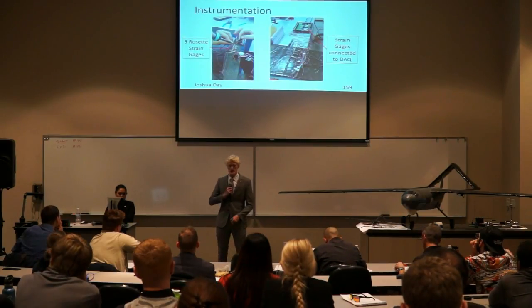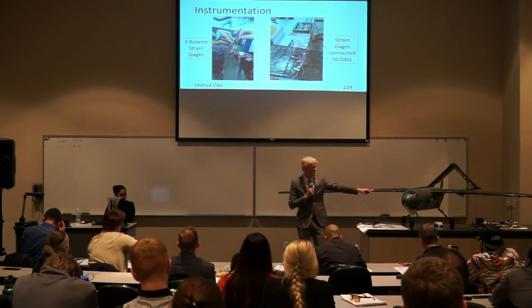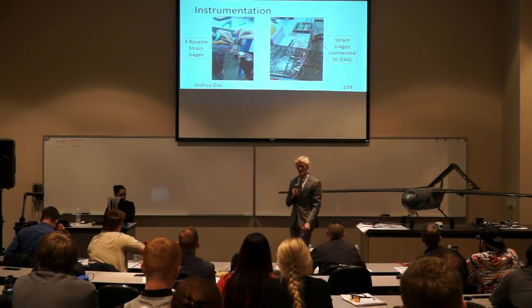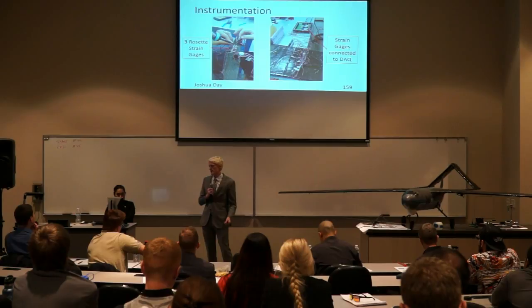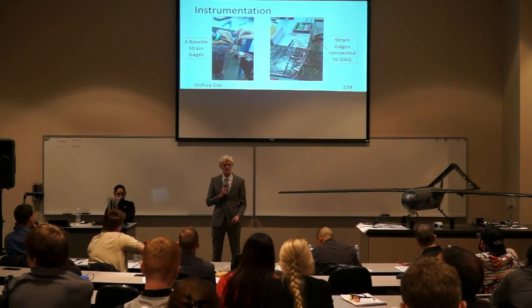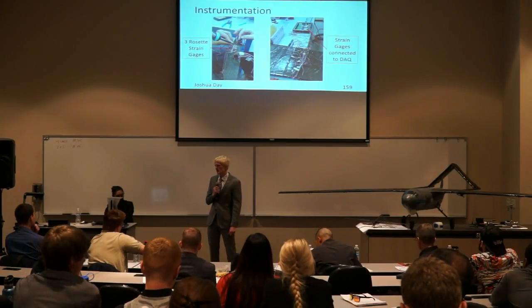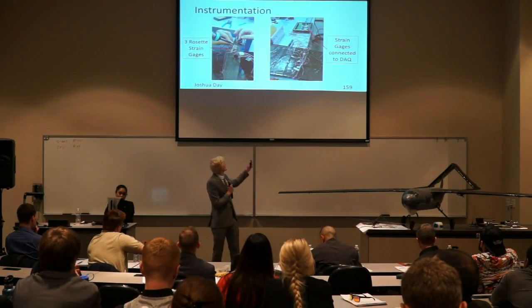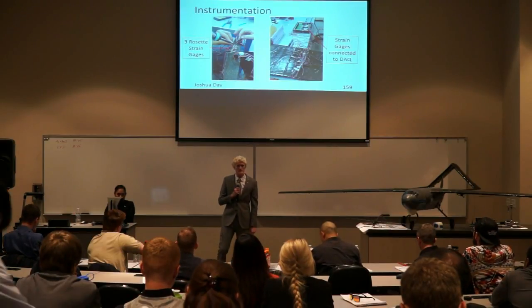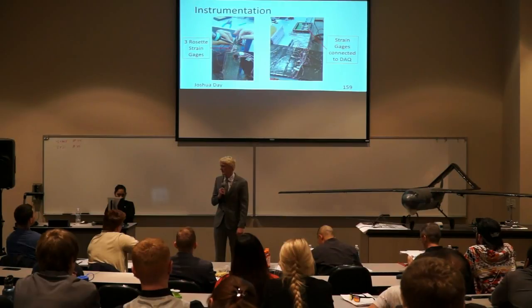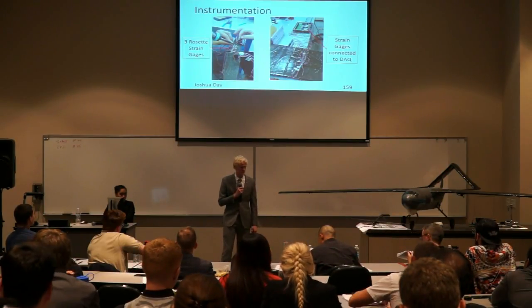To instrument our wing section, we instrumented this right wing up at this section, which was the originally calculated location of the most stress. We put 3 strain gauges on the top and bottom of both the forward and aft spar, as well as 3 rosette strain gauges, as shown here. And then those strain gauges were attached to a DAC, or data acquisition system, that was used to record the data from our structural testing.